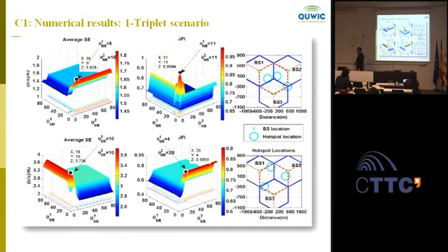One question, sorry. When you said the tilt is a maximum of 30 degrees, how is this tilt defined? In which direction, 30 degrees? Direction from the horizontal, so horizontal is 0. If you make your tilt even more than 30 degrees, depending on your radius, you're going to serve just maybe your neighbor. If I'm a base station with a height of, say, 20 meters, which is very large, and my tilt is 30 degrees and I have a vertical beamwidth of 10 degrees only, I'm going to serve maybe up to this distance only. After that, my antenna lobe won't be focused. They will be on the attenuation side of the antenna, not on the boresight side.